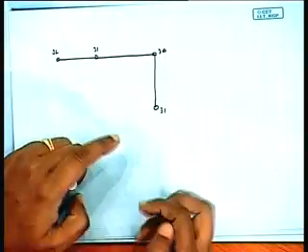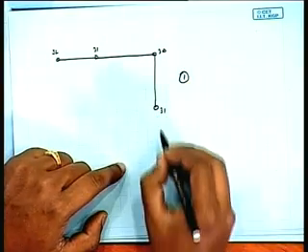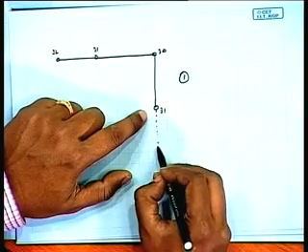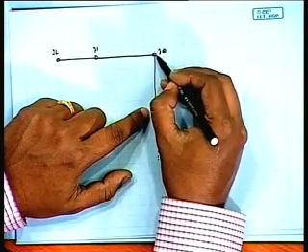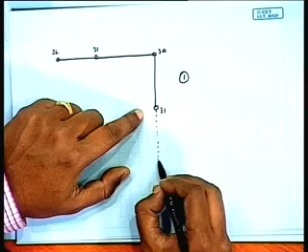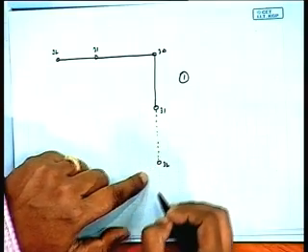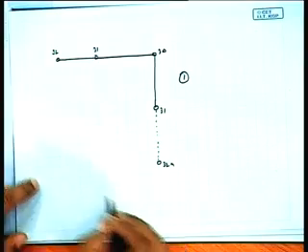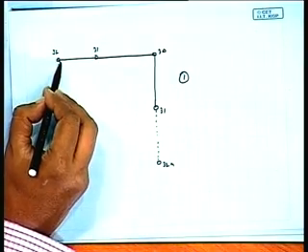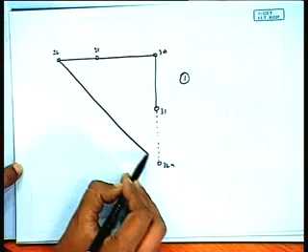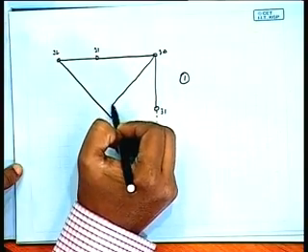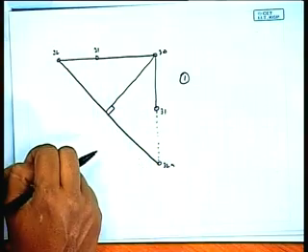Okay. There are two ways to do the procedure. One is, you can extrapolate this to almost the same distance at the 30th. So this is 32. Then you connect this, and this becomes the equipotential line here. From here you find the perpendicular and find the hydraulic gradient, isn't it?